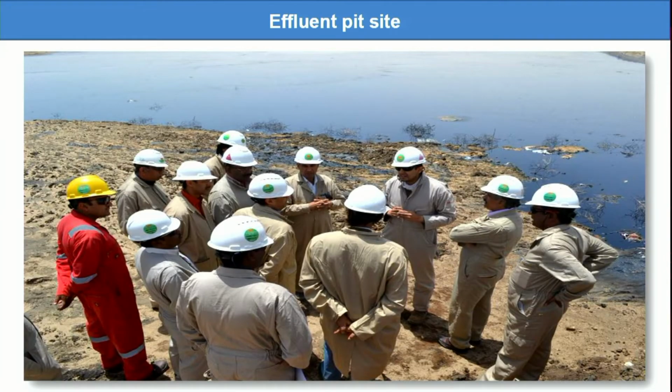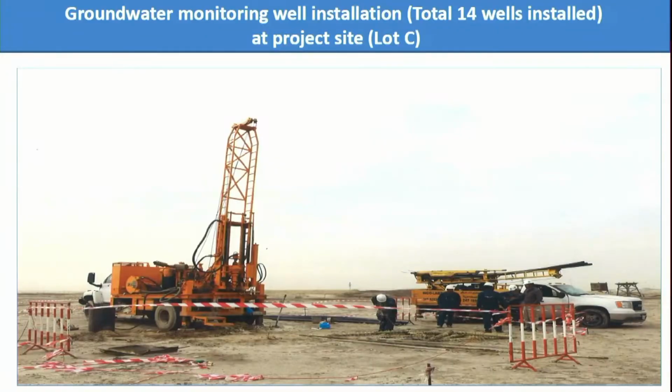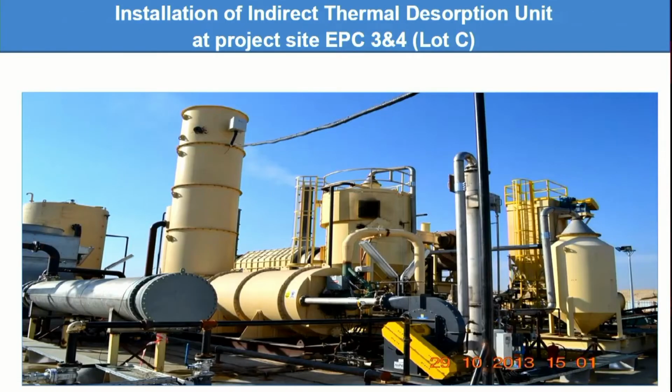Only once we remove the bombs, then they will allow us to do this work. After that, we have to remove this liquid oil, process this liquid oil, give this liquid oil back to the oil company, and then we take the contaminated soil for bioremediation. There was a lot of groundwater monitoring in the site, to check whether this oil is going down. And so we installed around 14 piezometric bore wells for testing.